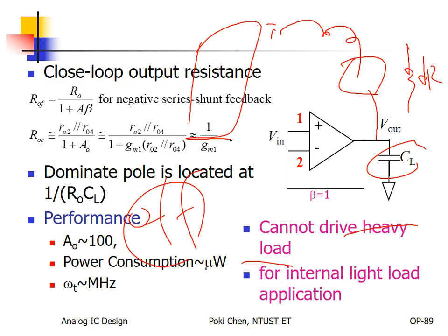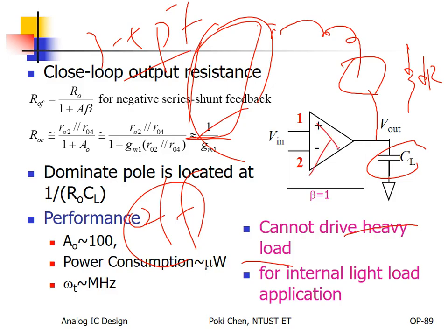Okay, usually even for the pad itself, maybe around 3 to 5 picofarad. Usually it means huge or at least very large capacitance on chip. Okay, and how about the off-chip parasitics, the resistance, the capacitance? Wow, it means what? You need third stage to deliver very large output current. Otherwise, you cannot make it.